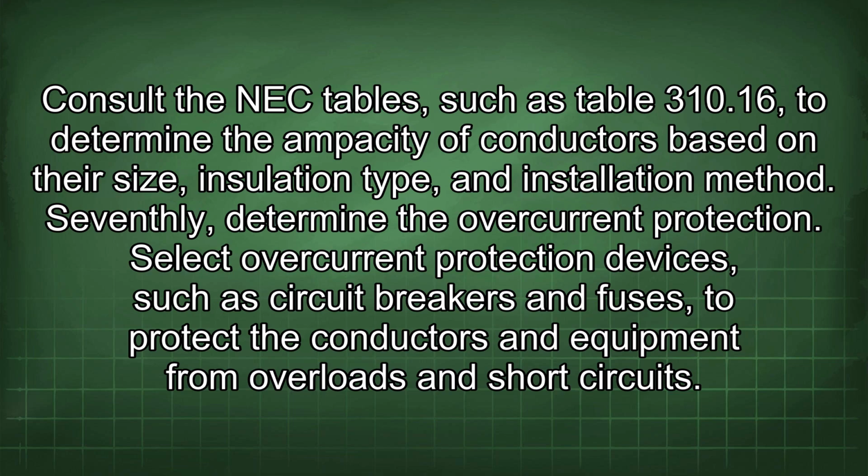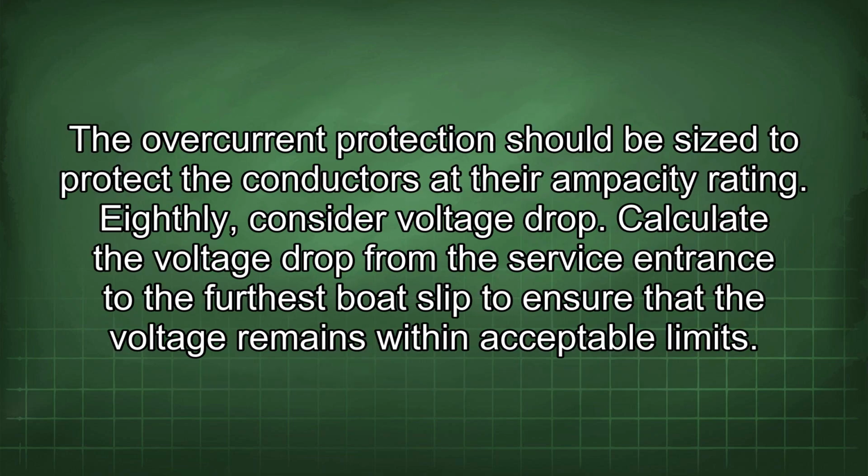Seventhly, determine the overcurrent protection. Select overcurrent protection devices, such as circuit breakers and fuses, to protect the conductors and equipment from overloads and short circuits. The overcurrent protection should be sized to protect the conductors at their ampacity rating. Eighthly, consider voltage drop. Calculate the voltage drop from the service entrance to the furthest boat slip to ensure that the voltage remains within acceptable limits.